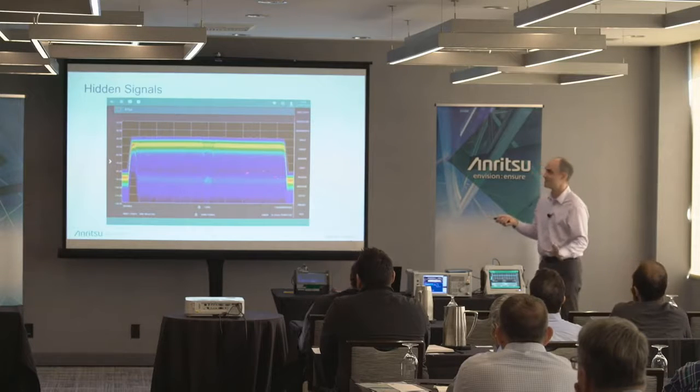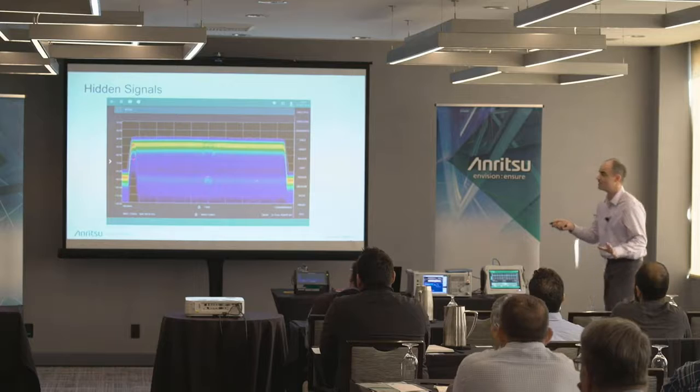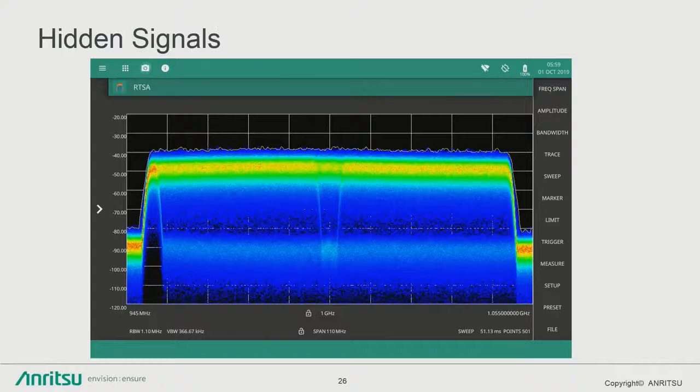So anyways, we've got a persistence right here, right? We're looking at a 5G signal, okay? What we see in the middle is probably our SSB, right? Because we've talked about how the SSB kind of resides in the middle. But you'll notice we've got some weird anomaly on the left-hand side, okay? This, I'll tell you right now, is interference.